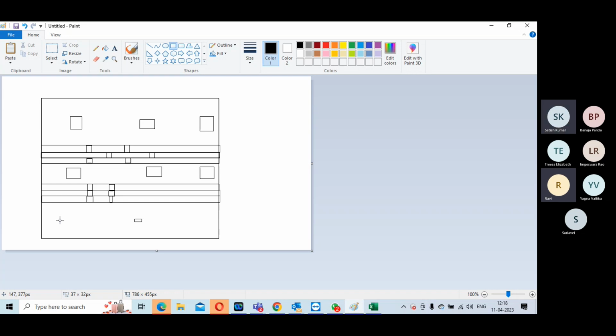I will tell you. First, it should be placed in the always on area. Isolation cell has to be placed in the always on domain. Yes, correct. But where? Isolation cells you will always place close to the port. Isolation cell should not have any driver after it. Isolation cell should be the last cell connecting to the port.